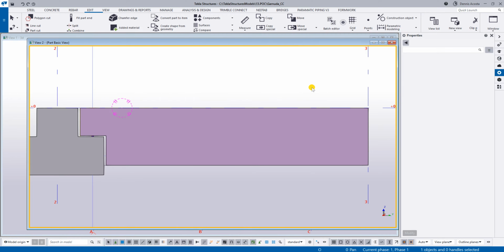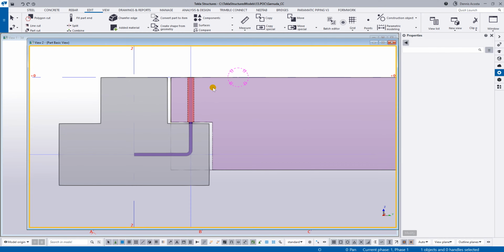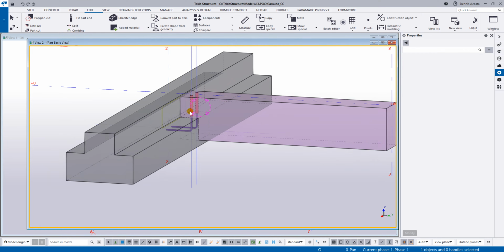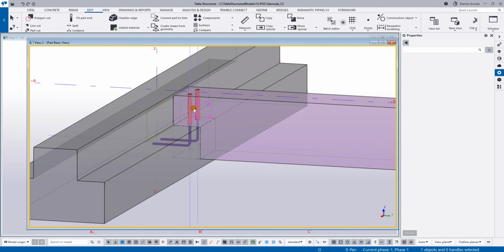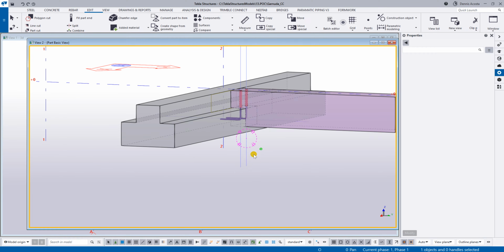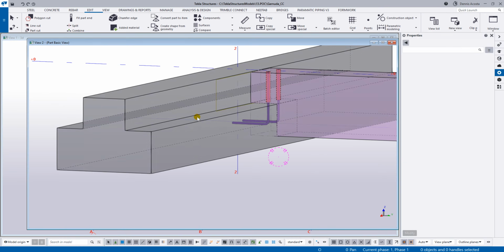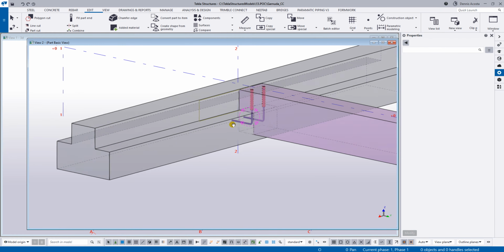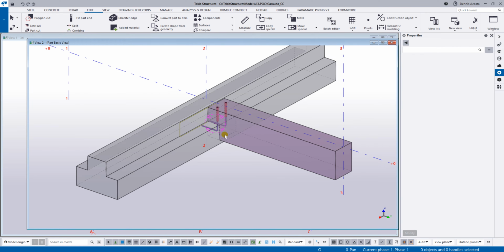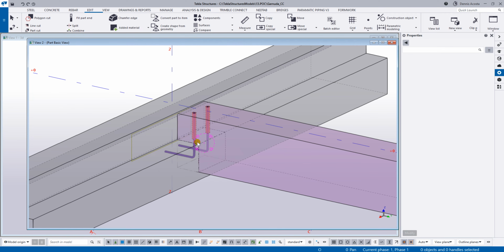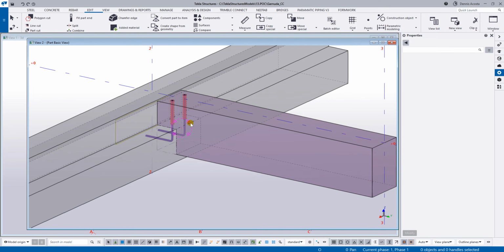Now, there you go. So that one is your connection. So let's do that one as our simple connection. Okay, this is a simple connection. Meaning, later on, once we select this, we add the connection, then it will cut automatically and it will add the dowel bar. Okay, so now, let's create the custom component for this. All right, so we did the model, a very simple model. Let's create a custom component.